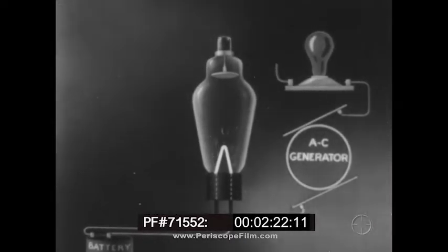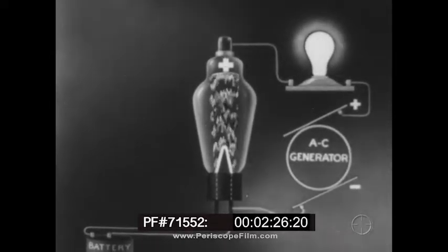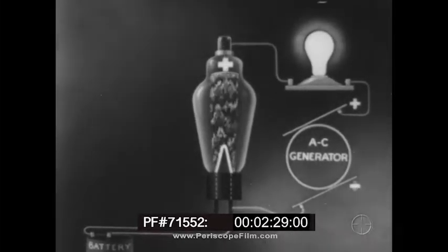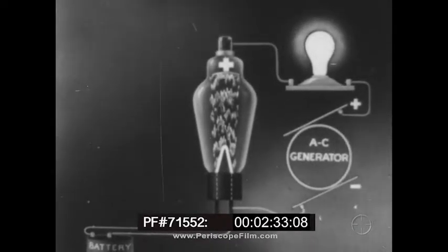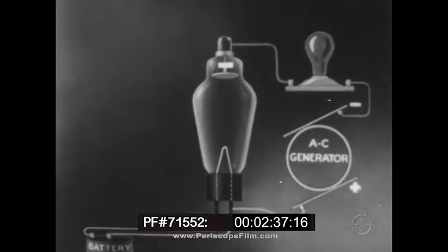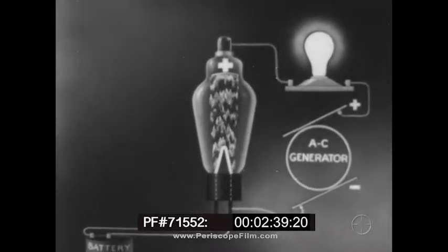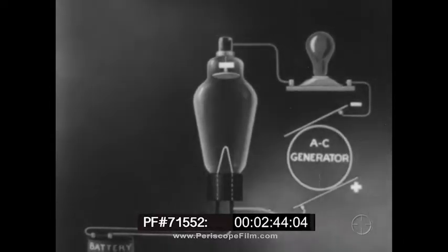We can do this merely by connecting an electronic tube in series with an AC circuit. As you study this circuit diagram, note that only each positive half wave of AC voltage will now produce a current when the anode current flows. In other words, because only the cathode can emit electrons, we have here what amounts to a one-way street.